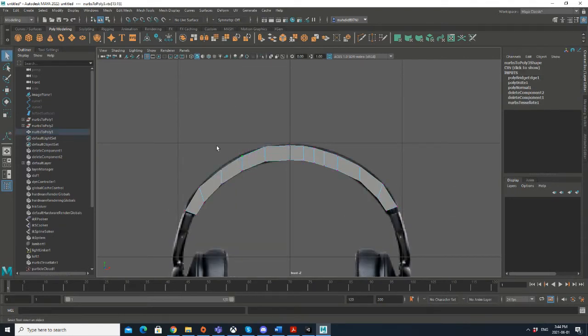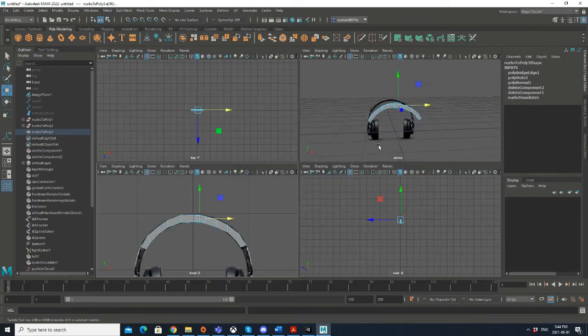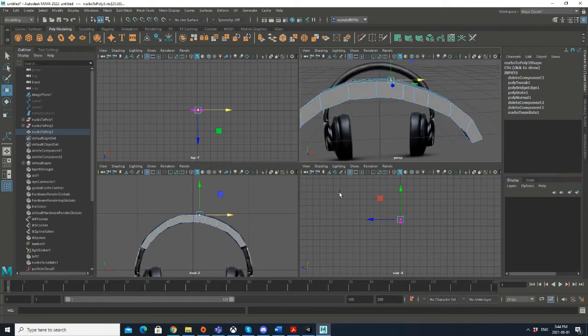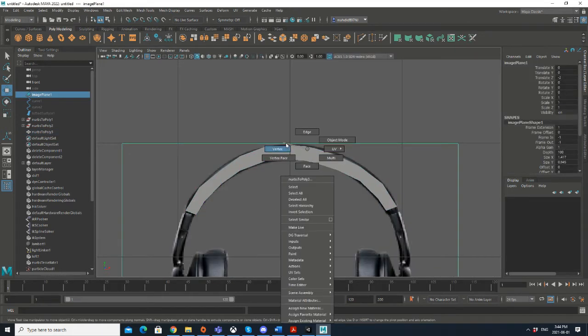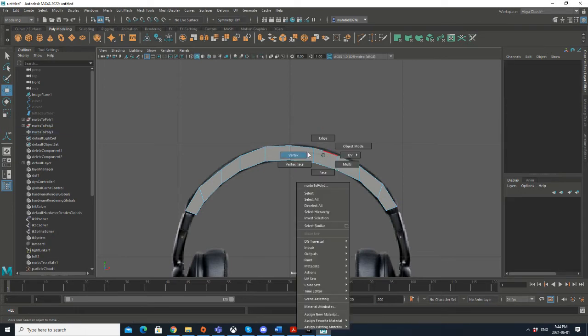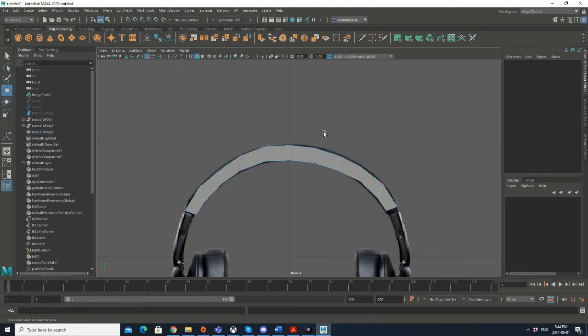Okay, so now we have designed our kind of curved object here, and as always you can go to vertices here and then move them in a way that makes more sense based on the object's shape. And let's just talk a little bit about these edges here as well. So if you are not happy with, for example, having these edges here and you want to have a kind of symmetric object, you can always, as you saw, select those edges and then delete the produced ghost vertices to have a more symmetrized object here.